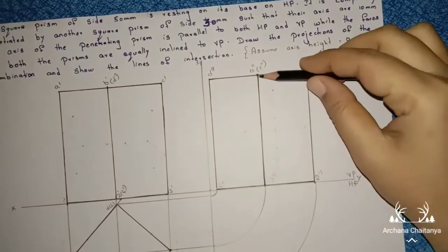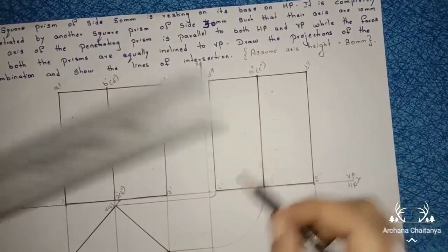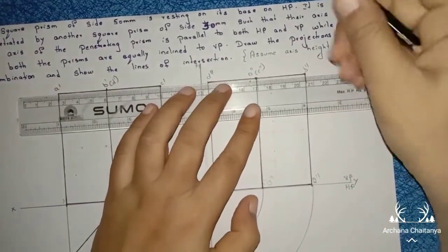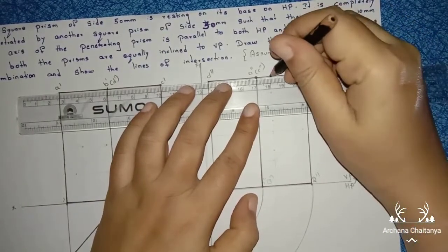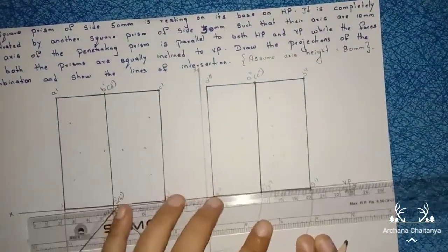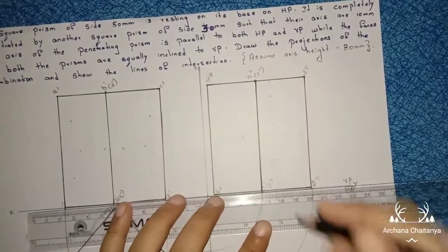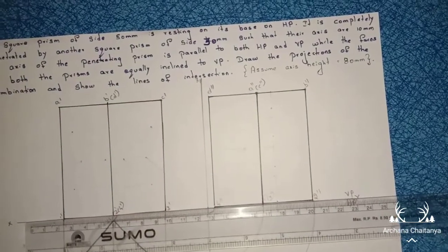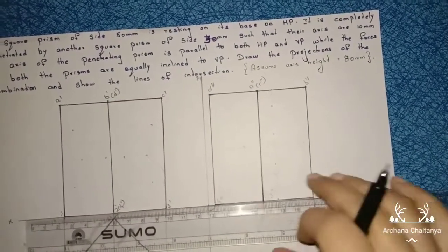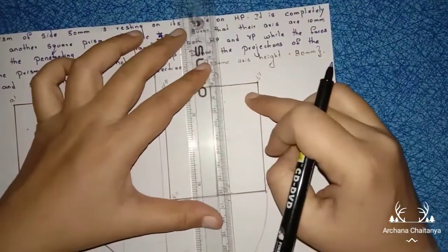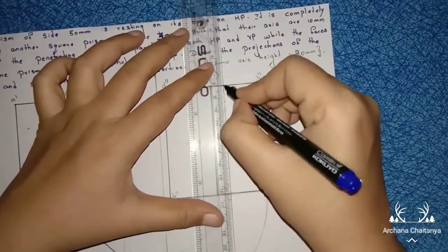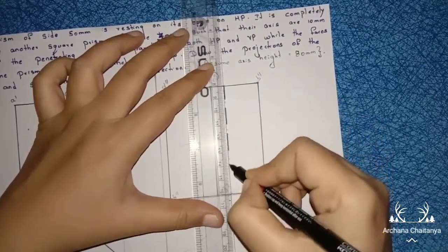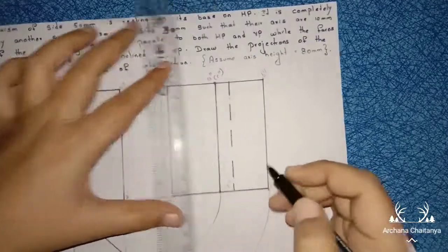Right, actually this is your axis line. Now from this axis line mark 10 mm distance here. Again from this axis line here also, top face and bottom face, mark 10 mm distance. They clearly mention that axes are 10 mm apart. After marking 10 mm distance, now through that point construct the axis line. Axis line should be dash dot, construct the axis line.